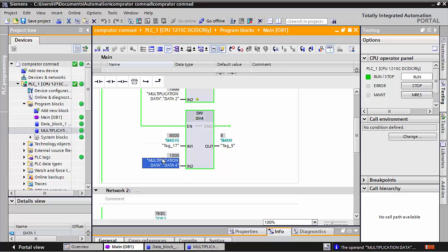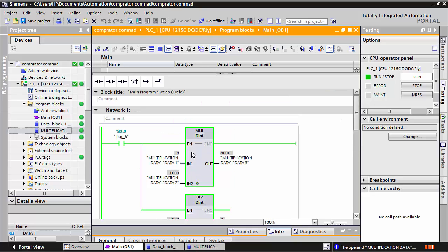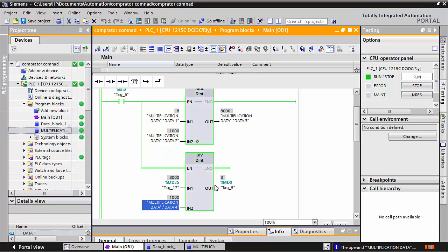And if you put this formula multiply in the program, you can get continuously that 8 seconds. If you like to write, you can write 8 seconds here, and you will get 8 seconds. And this data register you can also take at the HMI, and there you can see which data you wrote for the program. I hope you will understand about this command.